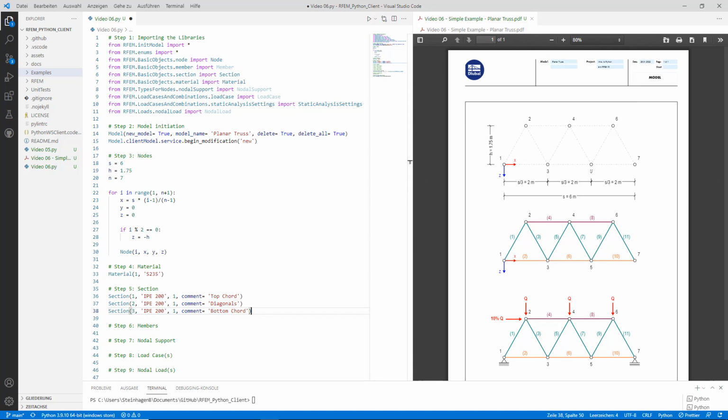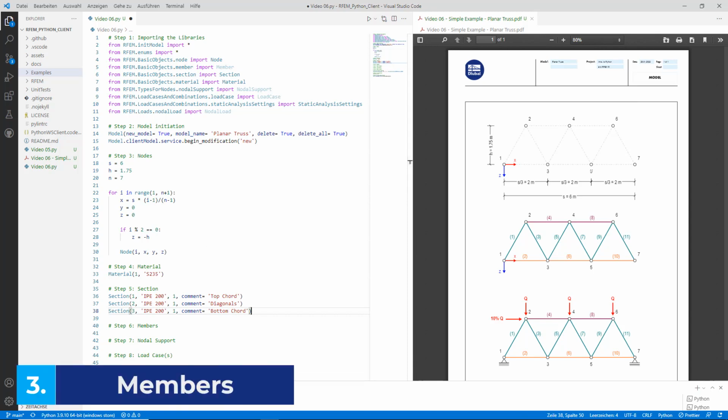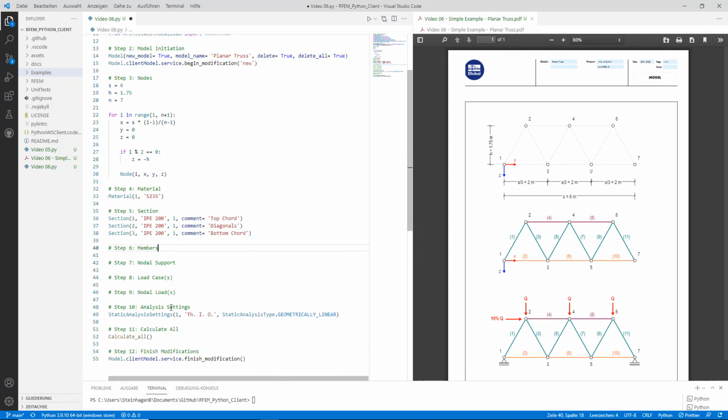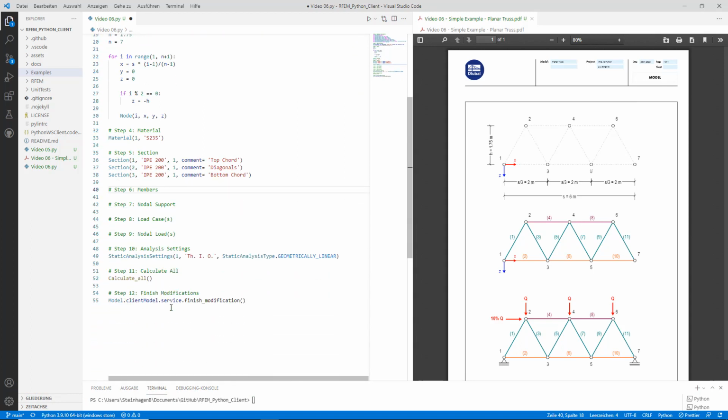Now for the algorithm for modeling the beams. Note, there are many options to do this. For small structures we can define each point and member explicitly, so-called hard coding. However, the bigger the structure gets, the more tedious this becomes. Therefore, we want to try to follow an ordered numbering procedure, such as the one shown.